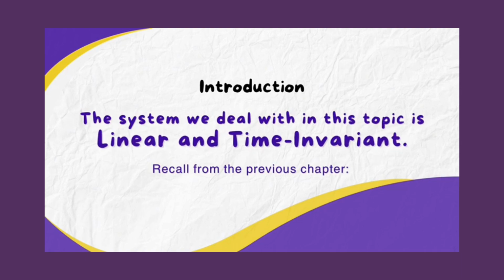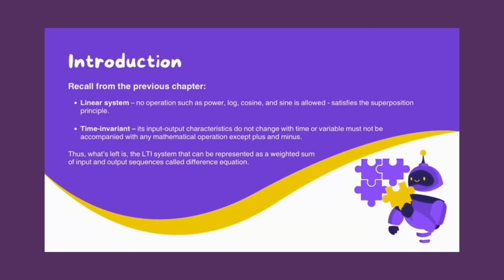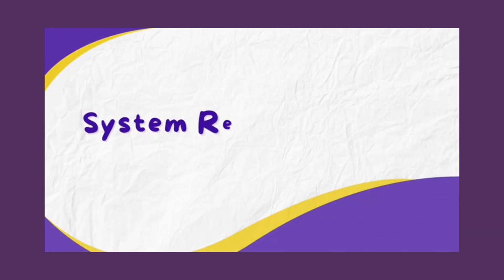So, let's recall from the previous chapter. We learned that in a linear system, no operation such as power, log, cosine, and sine is allowed, and it satisfies the superposition principle. In a time invariant system, its input-output characteristics do not change with time, or variables must not be accompanied by any mathematical operation except plus and minus. Thus, what's left is the LTI system that can be represented as a weighted sum of input and output sequences, called a difference equation.